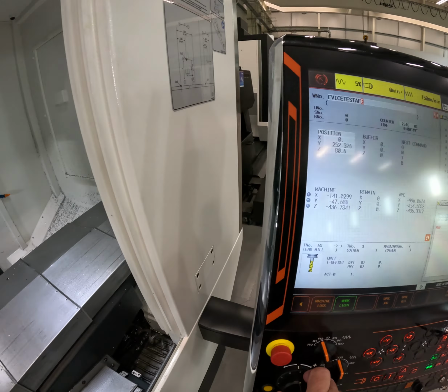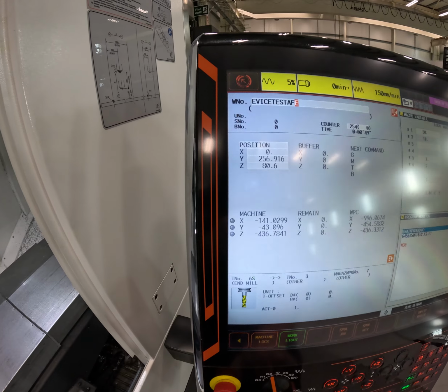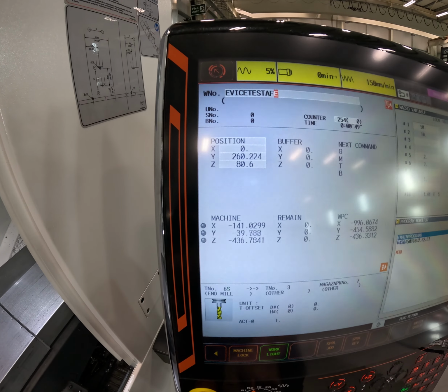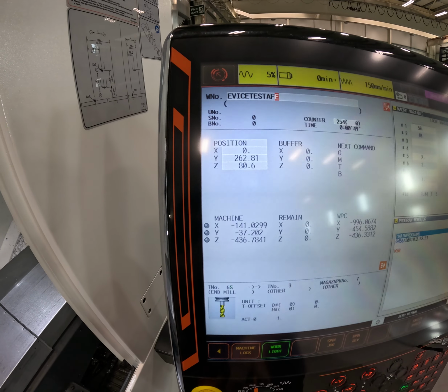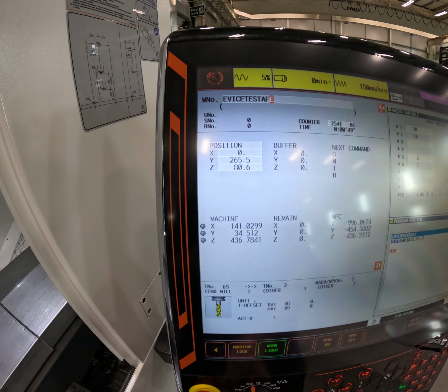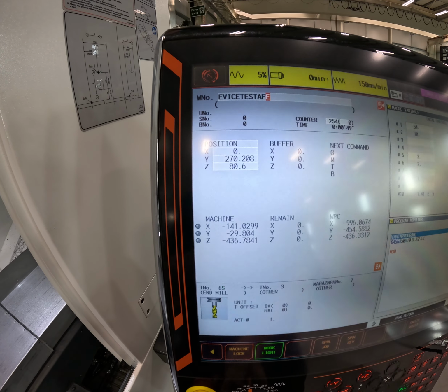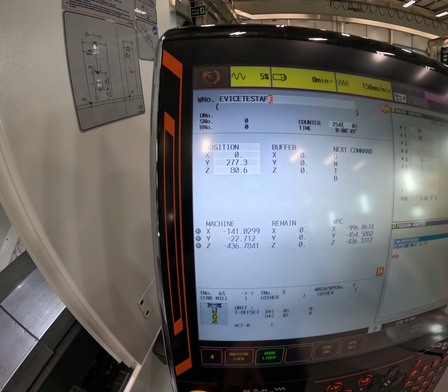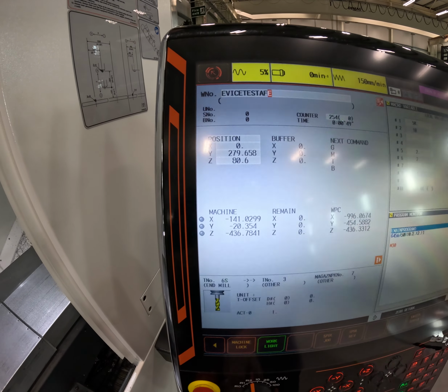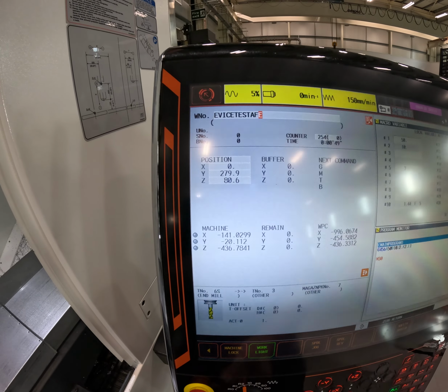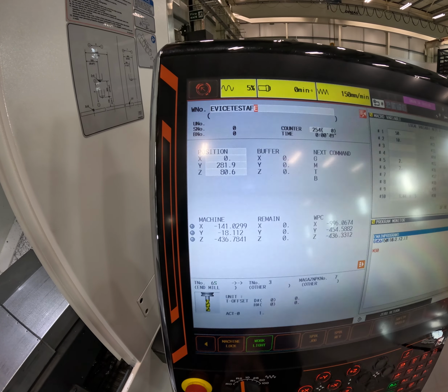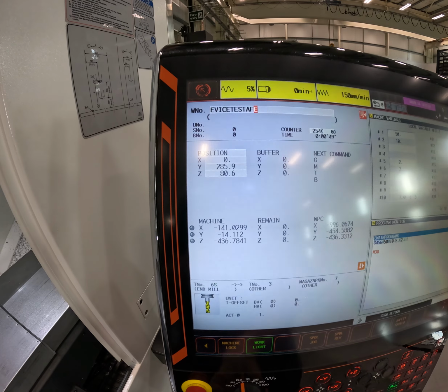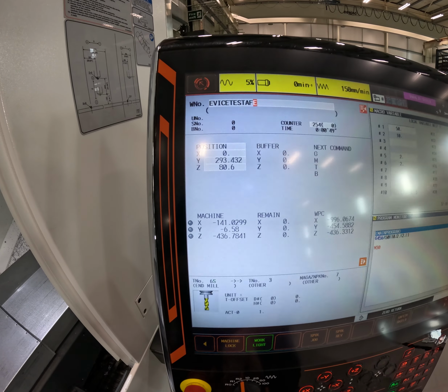It's important to do this because we have no parameter in there, so it's searching for a parameter, it's searching for a home position. There are no soft limits with this. If you change our parameter, we've opened it up and it's in like a home teaching mode, so you can crash this machine. It's important to take this slowly.